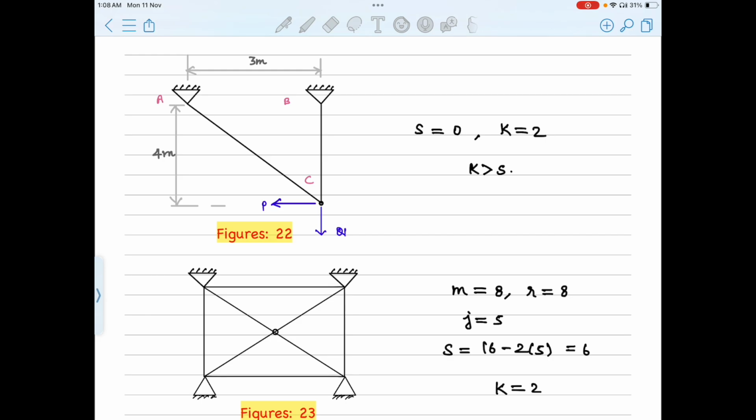From this example, what we learned is if we choose displacement as unknowns, one needs to know what is the degree of kinematic indeterminacy of the structure. We are going to explore the kinematic indeterminacy in the upcoming video, but why should we take this much trouble to solve this statically determinate truss by displacement method? That's a good question. We see that if we are concerned about just forces, we can solve the problem by force method, avoiding rigor by not choosing the displacement method.